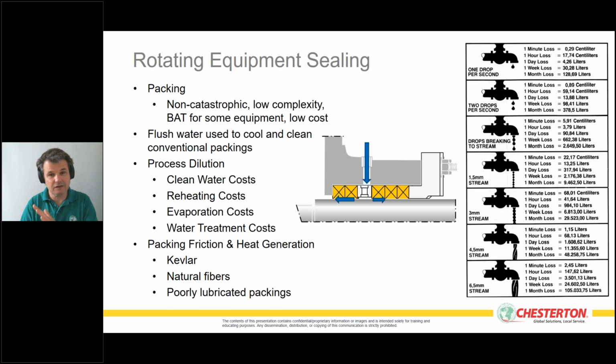First of all, the water itself needs to be prepared, so it costs money. When this water goes into the system, the medium needs to be reheated, or the water needs to be evaporated again. But as well, and something whose effects I can show you more clearly, water that leaks out of the pumps goes to drain and has to be treated in a water treatment plant, and this is quite expensive.